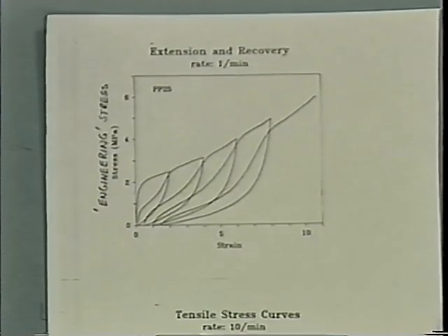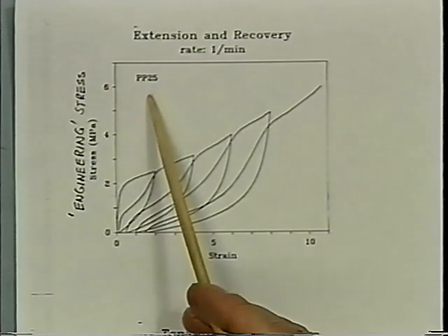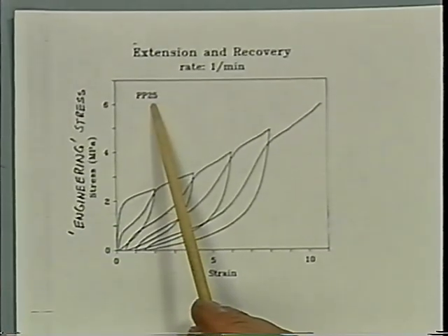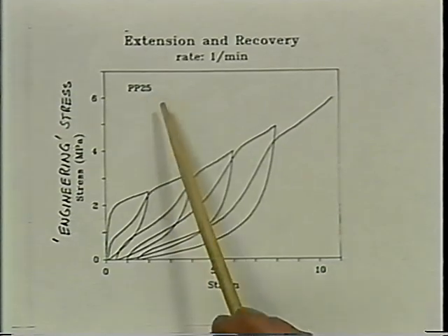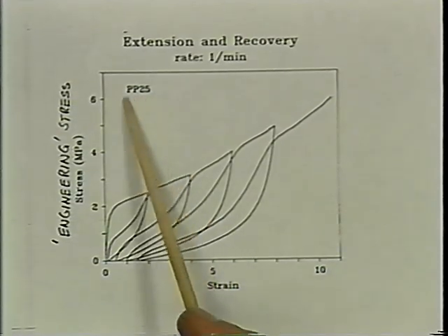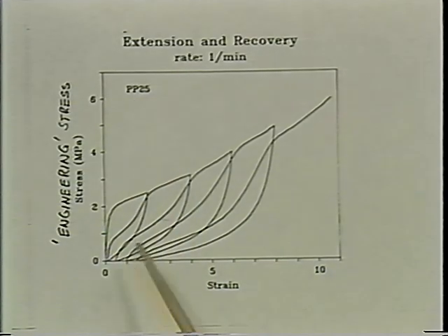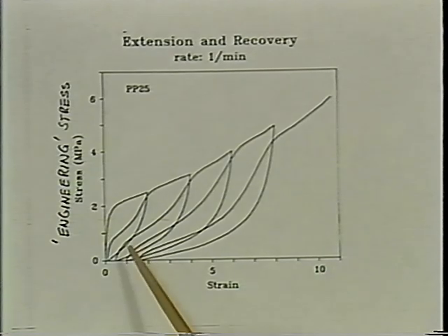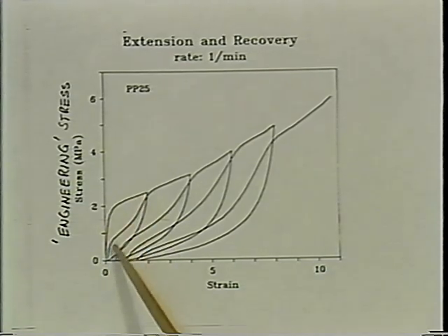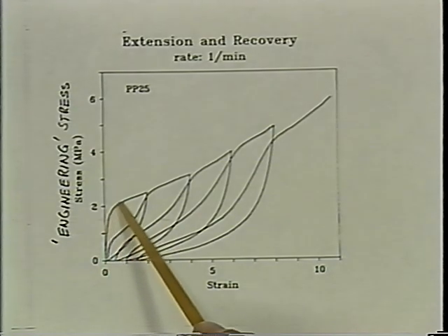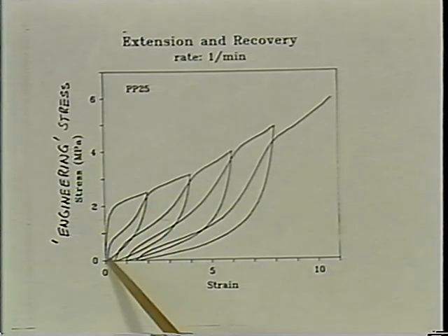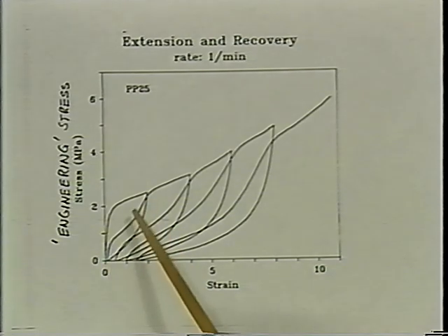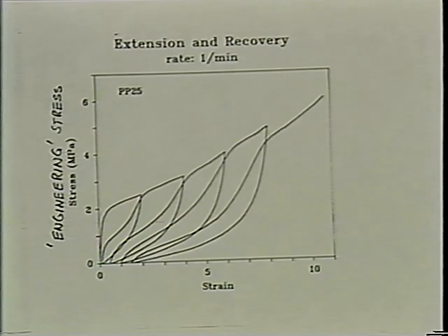The mechanical properties of one of those systems, this is the polypropylene polymerized at 25 degrees. Professor Chen and his group produced different systems at different temperatures. So this is the system polymerized at 25 degrees, and with some small load, it deforms. Like here, with increasing strain, the stress grows, and then it somehow starts flowing. And then when taking off the strain, it goes back pretty much. It's very elastic, but some breaking has occurred. That's probably the longer lamellar region, the bigger crystals which are broken in the system.